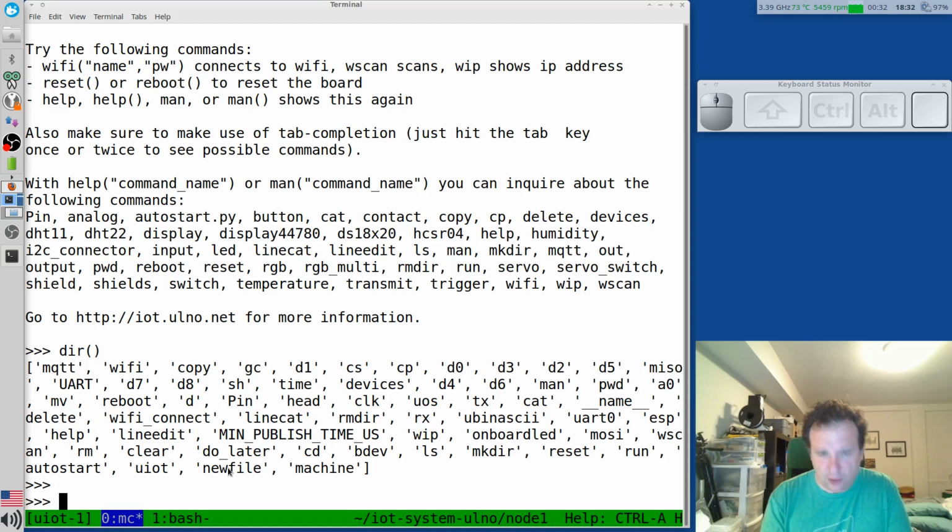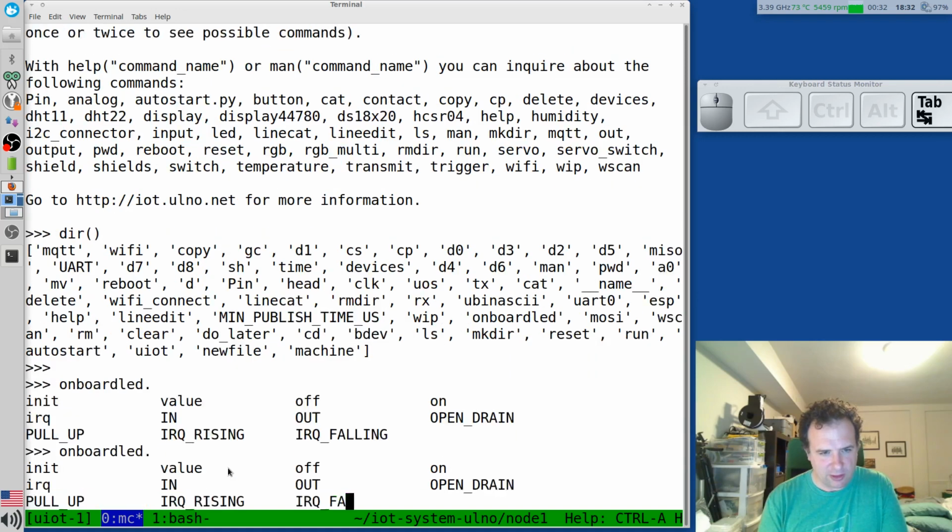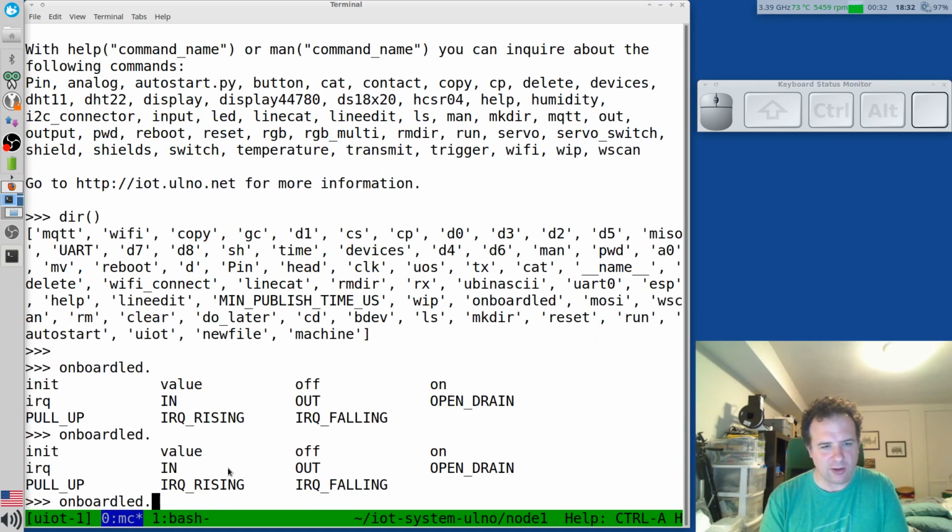So, and as I said, there is an onboard LED. So let's type that. You can actually also complete commands with just typing tab. See? Then if there's only one option, it does this automatically. Or if you just put E on, even that is already enough. So onboard LED. And also here, if we have commands, this is Python, then you can see with pressing the tab key the commands which are actually in there. And see there's an on command, there's an off command, but this doesn't switch the LED yet. So first you have to do an init.